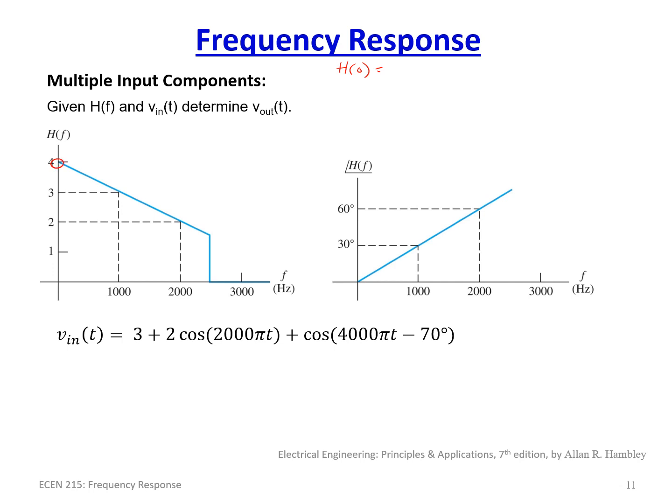So that's equal to 4 volts per volt, and it has a phase angle of 0 degrees. We have H at 1000 hertz, and that is equal to this intersection point here, 3. So we end up with a magnitude of 3 with a phase angle equal to 30 degrees. So we have that.